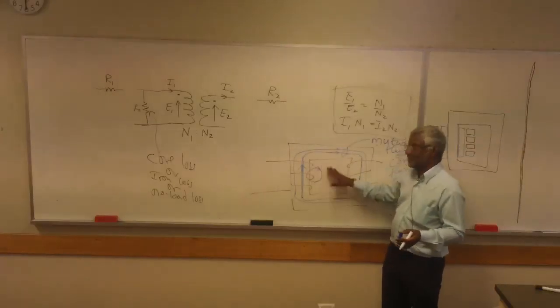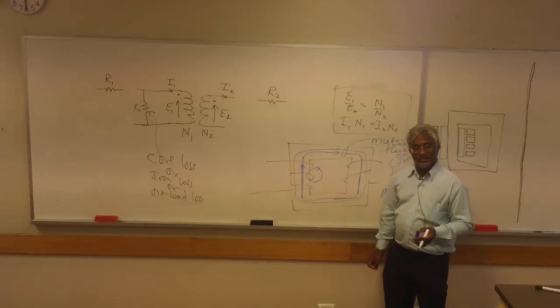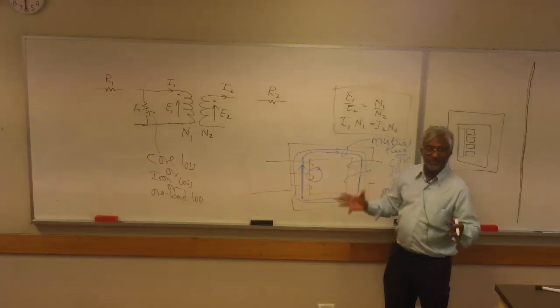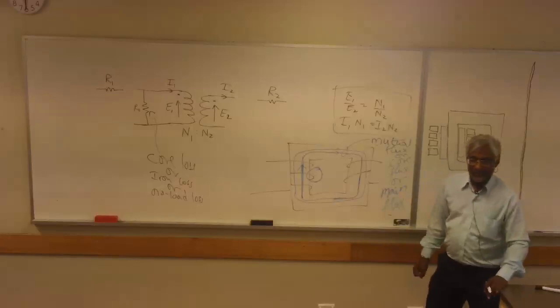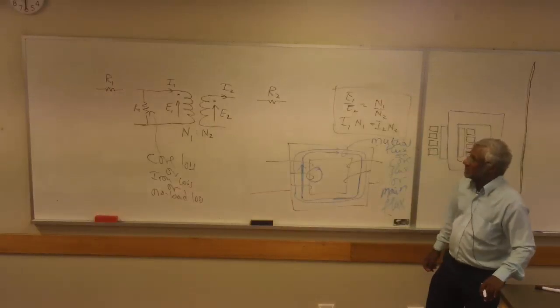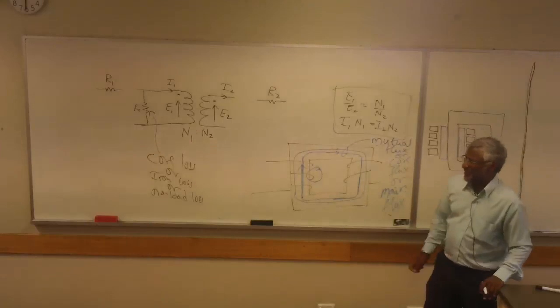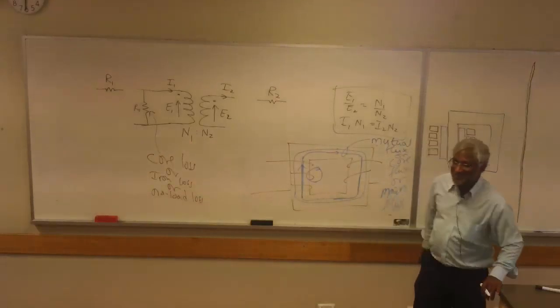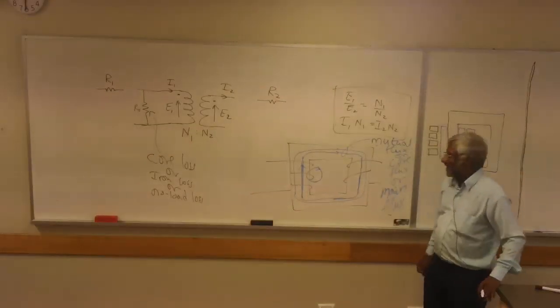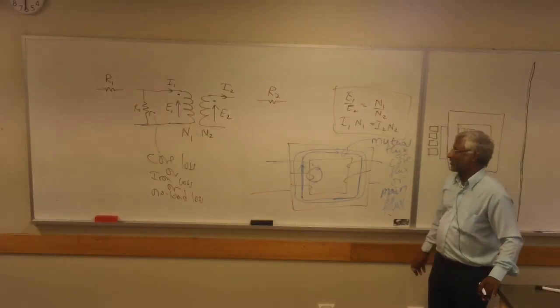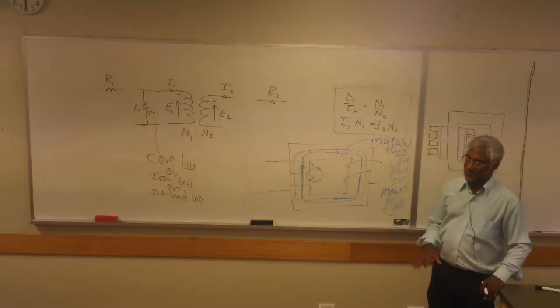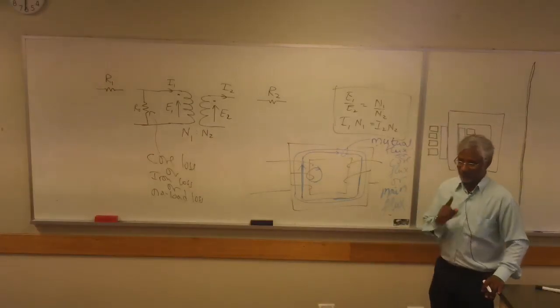Of course, this is air here. What percentage, roughly? 99? I'll go for about 97. It depends on a few things, but practical transformers would have leakage flux of the order of a few percent rather than 1%.